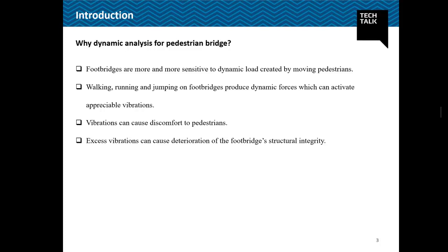The dynamic loads coming on the bridge will be walking, jogging, and steady state crowd loading conditions. The primary objective of the dynamic analysis is to determine the effect of dynamic loads on the structure's dynamic response and its influence on the users. This is the main gist of why we perform dynamic analysis of pedestrian bridges.